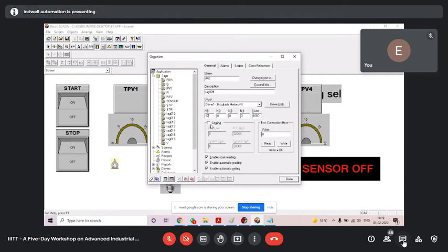For scale, you see they have given scaling. I click this scaling. PLC high value, system high value means PLC high value and SCADA high value. 20,000, 20,000. Now, if I want to make it a multiple of 10, what shall I do? In PLC, it is 20,000. In SCADA, I shall make it 2,000. So now it is a multiple of 10. In that ratio only, data will be scaled here. It is done. Now I go next.